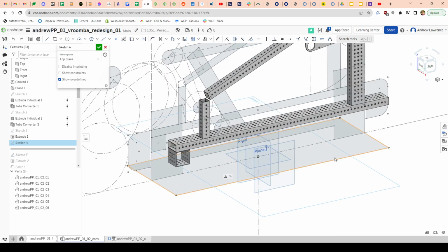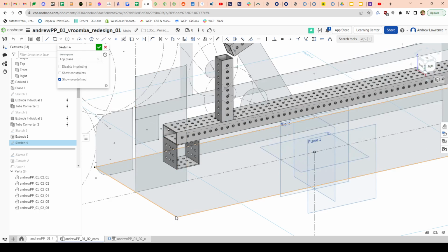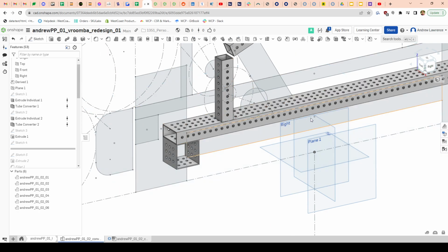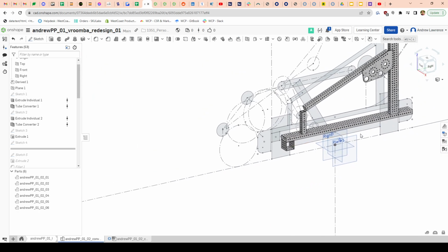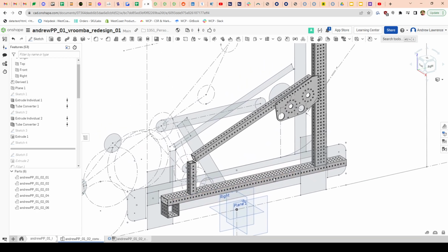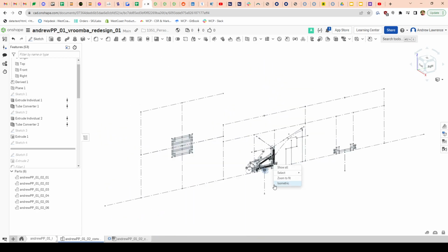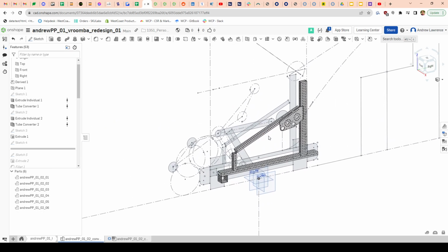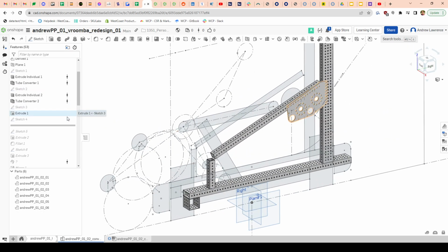But instead, what I do is with this flat rectangular sketch, I effectively make a floor that is centered on the origin that is the exact size of my main base. So when I go to put parts in, I will reference these parts as a mate to this corner of this sketch. And I'll show that when we get to the assembly. So it's a little cheat method I've found. An easy way to get some reference geometry into the assembly without having to actually make a dummy part. A lot of people make dummy parts, and I'm not a fan of that.